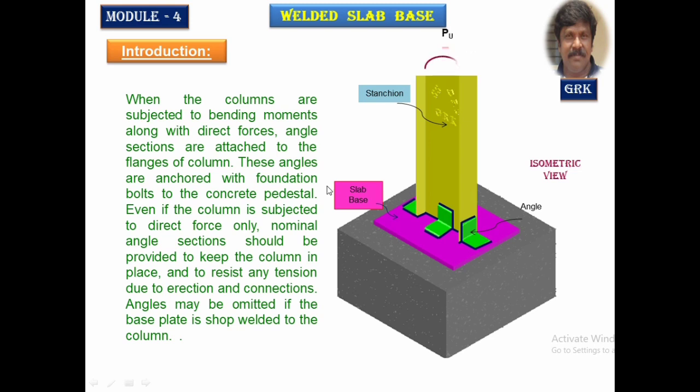Even for the earlier cases, if you are interested, you can use the angles or you can remove them. It is left to the discretion of the designer. When it comes with moment, it is better you provide the angles here to keep the column intact with the slab base and in position.